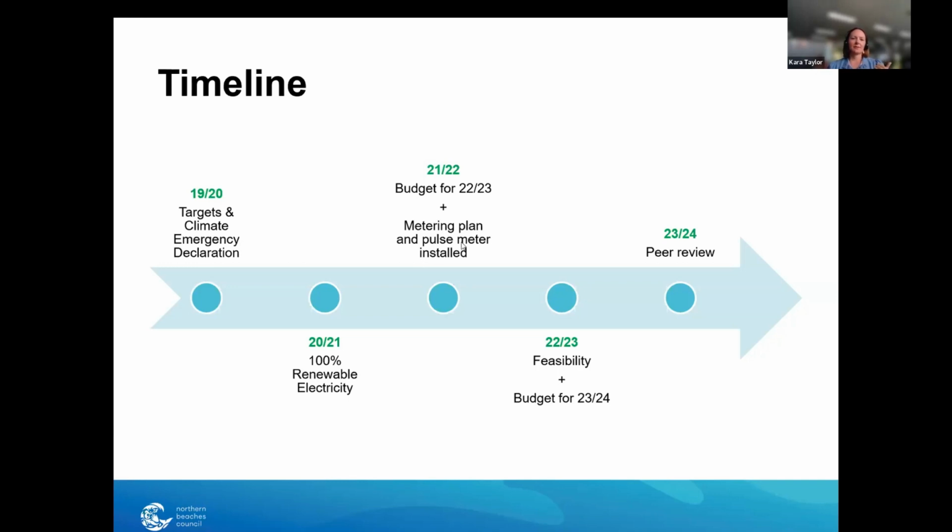So after going to one of the workshops, I was like, what do I do? And they said, make sure you're getting enough data. So we got a consultant to do a metering. It's just a very brief report for a metering plan to tell us the best way to get that data. And the cheapest, simplest, most effective way for us was to put a pulse meter on our large gas